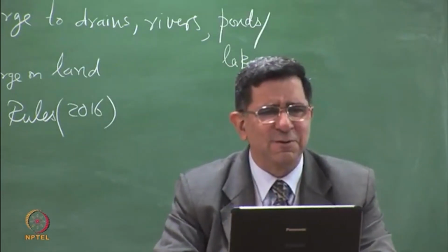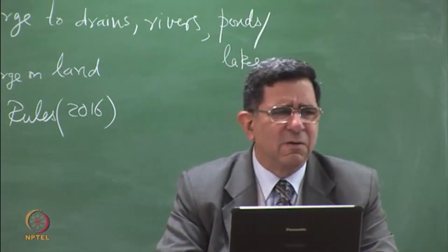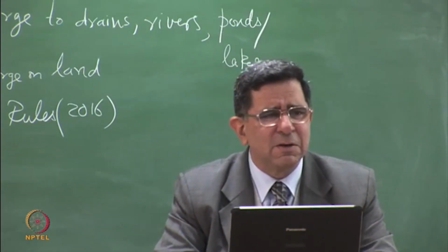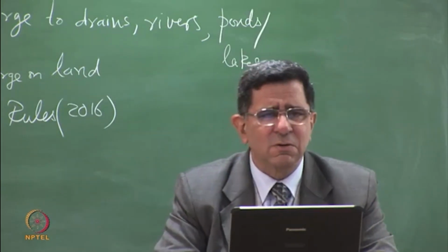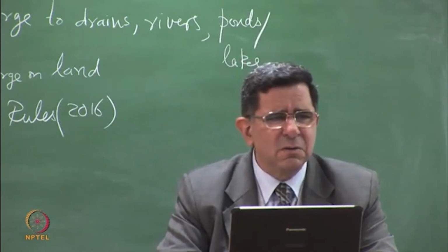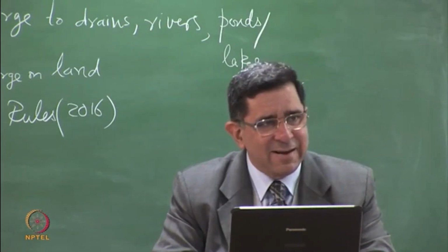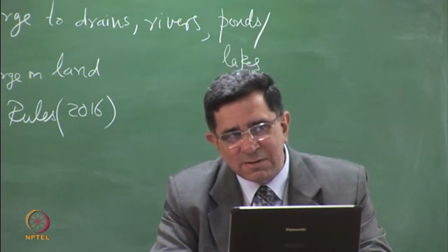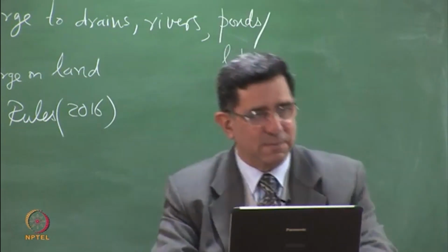Test for dissolved salts. And suddenly he tells me, sir, heavy metal is 4 ppm and the limit is 3.5 ppm. Is it dangerous? I said, what about the total dissolved salts? Oh, sir, the limit is 1000 and we are measuring 20,000. So get the right constituent. Please look for the right constituent. I may have given you a list of 30, 40.